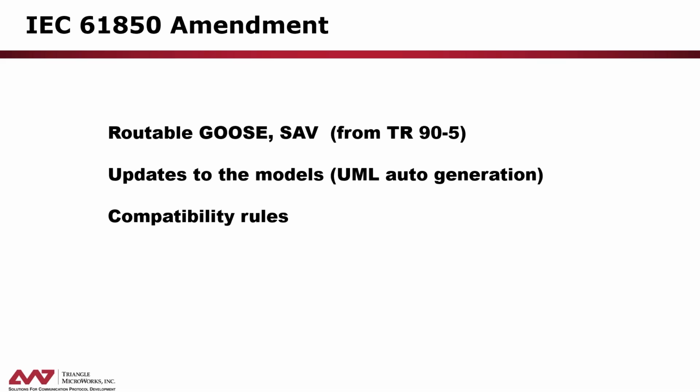Well, in the last 10 or 15 years, 61850 has expanded outside the substation. In fact, edition 2 changed the entire name of the standard series from substation to system, acknowledging that we're having broader scope, particularly in the distributed energy resources world. The DER world is much more dynamic, much more distributed, as the name says. So we need to be able to reach these systems outside the substation.